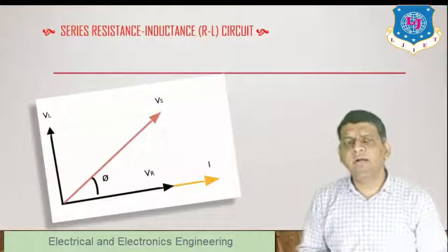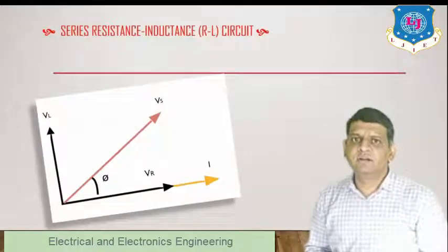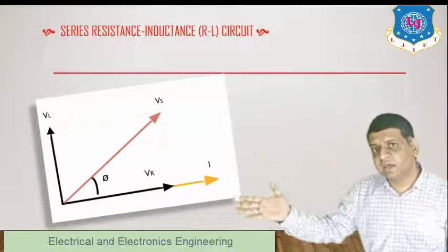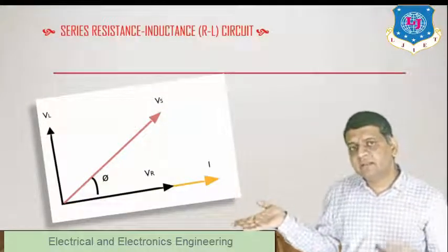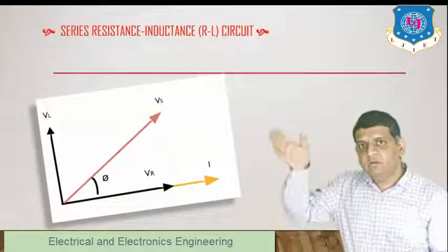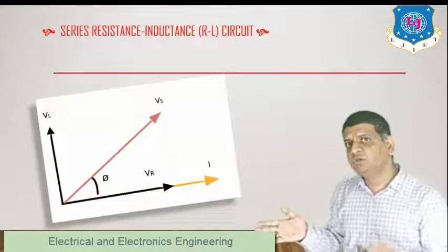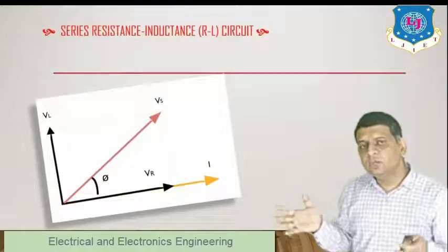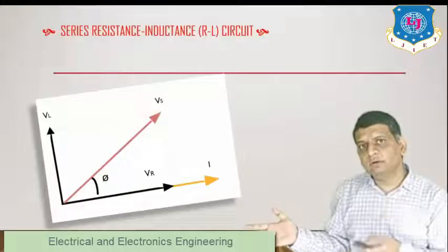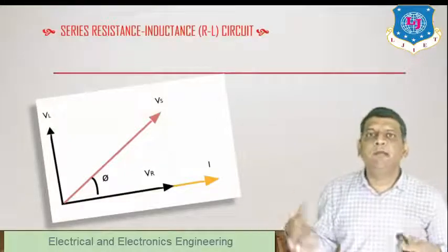From this we can go into more detail using our phasor diagram. You can again observe the phasor diagram. From this you can straight away see the triangle, where the x-axis is defined as the voltage drop across the resistance, and the y-axis is the voltage drop across the inductor. Once you take this triangle, you will find the diagonal, which is your applied voltage V.